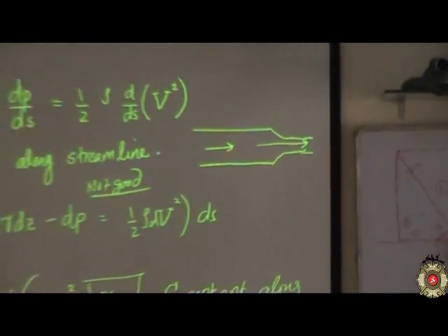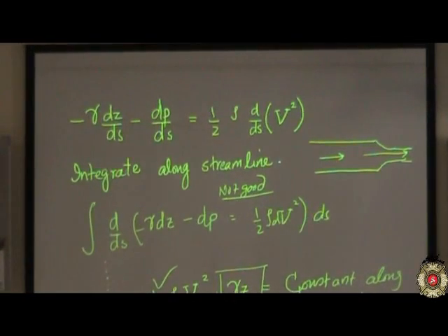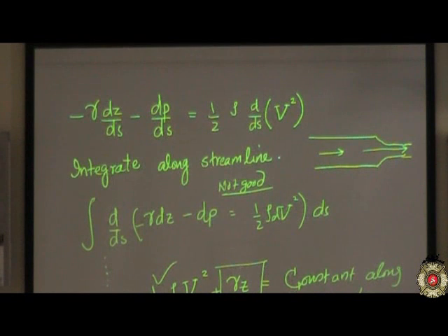So if there is a restriction or a nozzle effect, this pressure would decrease or increase? Decrease. Why? Because the velocity is increasing, and this is the law it would follow. So the question basically comes in, if the velocity is increasing, how much variation is there in the pressure field. These are the analyses done by this guy, and a mathematical proof for how a fluid particle would behave in this situation.